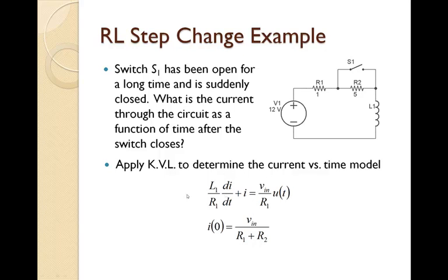We developed our differential equation, and this is what we came up with, and we also developed our initial condition to solve that differential equation, and we came up with the same thing again by looking at how the circuit behaves both before the switch is closed and right after the switch is closed, and using the fact that an inductor, if it's been operated for a long period of time, acts like a wire, but the voltage across it can change instantaneously when a step change occurs, like closing this switch. But the current passing through it cannot change instantaneously.